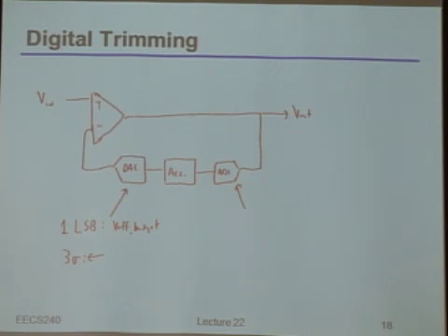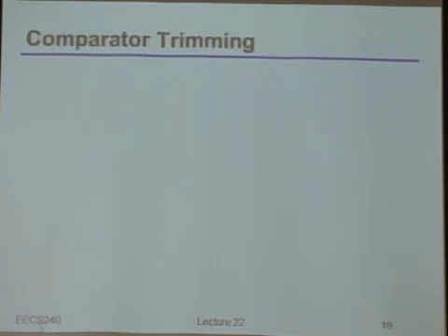So, by the way, what is 1 bit of resolution? What kind of circuit is that? Or 1 bit ADC, excuse me. It's a comparator, right? All right, so now let's see why you can actually get away with just 1 bit of resolution. And of course, this works most nicely when you're trying to cancel the offset of a comparator in the first place. Because, hey, you have a comparator already, so we don't have to rebuild another one. Now you can take the ADC and replace it with a comparator.